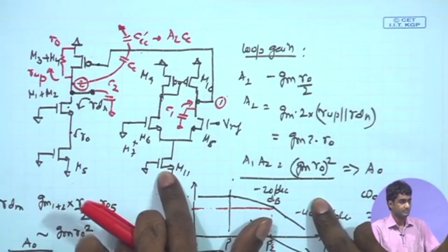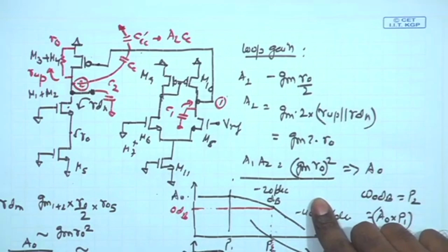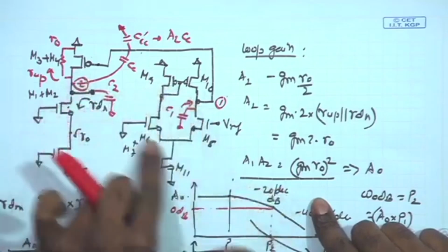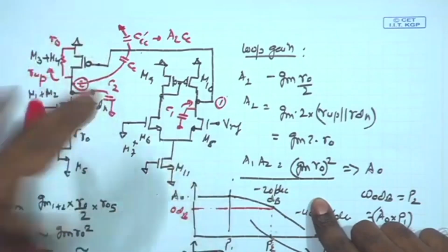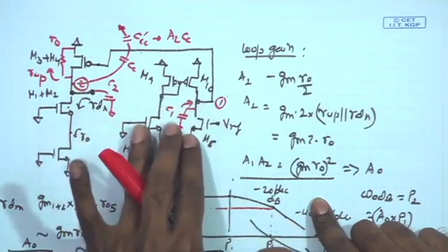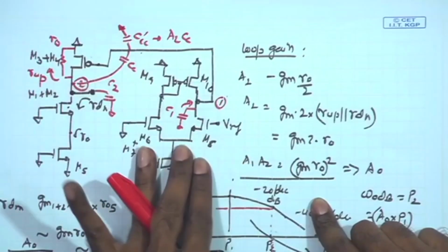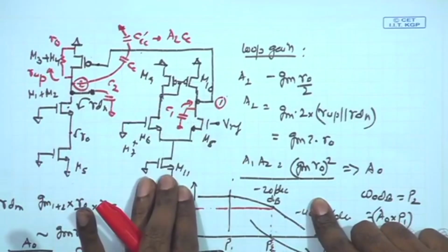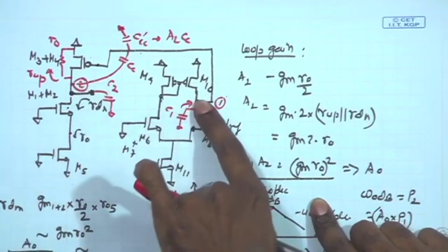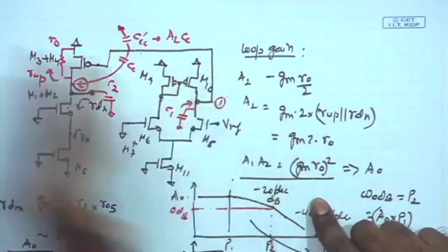bias current in this stage, and that will help. Here noise constraints are also less critical. In the main differential amplifier, you have a noise constraint because of which you cannot really reduce the bias current too much, but in the common mode feedback amplifier it is a little less critical, because whatever noise comes, it comes in the common mode. Because of that you can reduce the bias current of this one more aggressively, and you can apply longer channel length as well, so that the RO of this stage becomes the dominant one. That will help you in pushing pole 1 to low frequency.